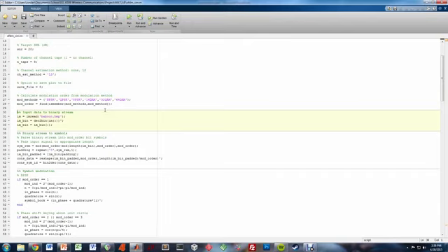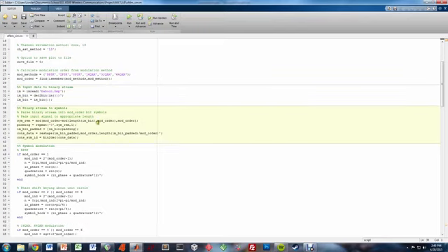So the first thing we do is read in the image and translate it from a three-dimensional array, where you have the XY dimension along with each RGB component, into a single binary stream. This binary stream is then mapped from bits 1 and 0 to symbols, which correspond to the modulation order.